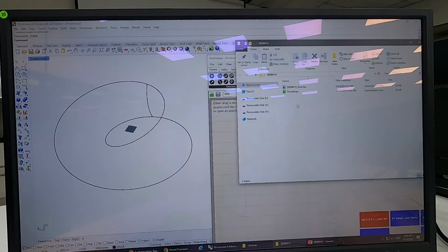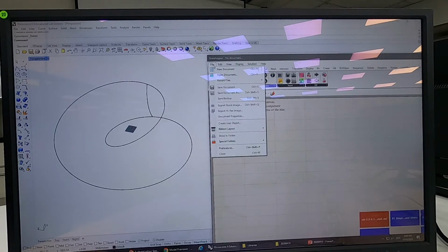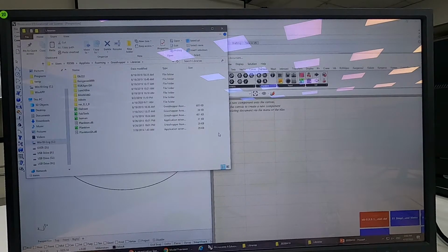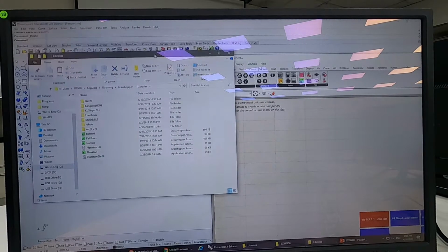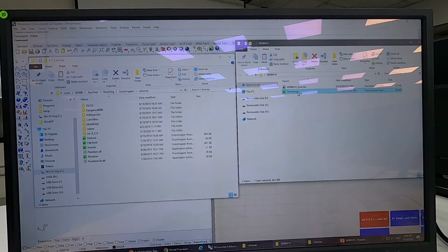First, I need you to open Grasshopper and go to File, Special Folders, Component folder. It's a plugin library here. We could place this Triceratops, a plugin provided to export mesh to JSON format.